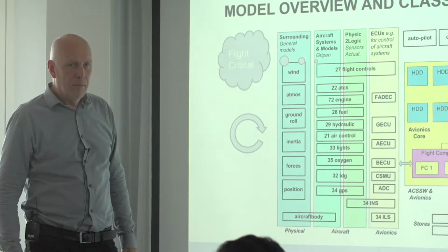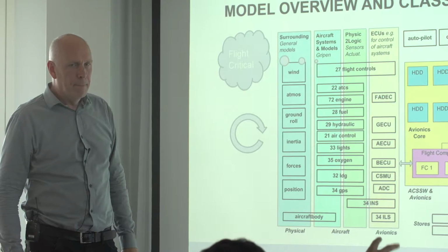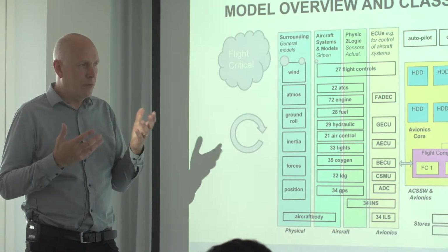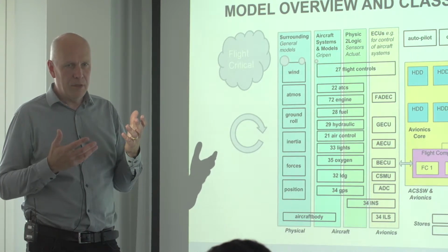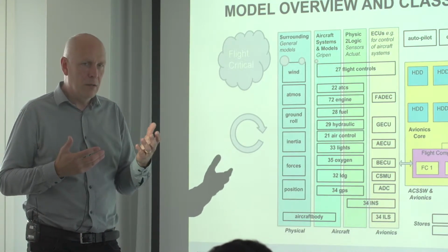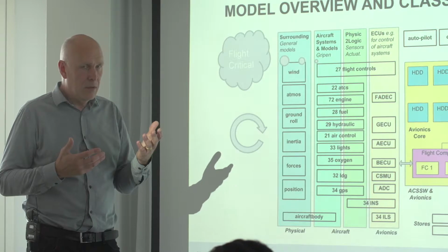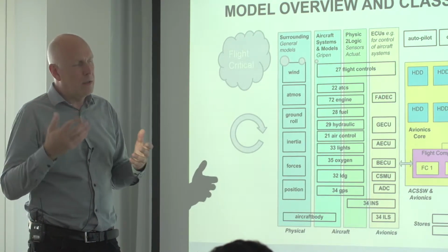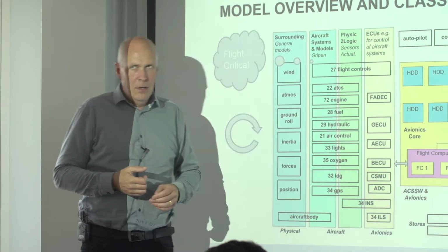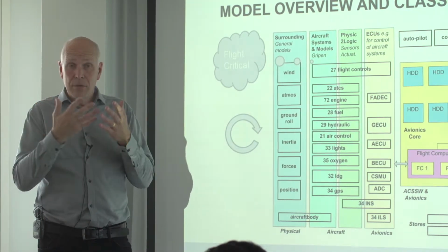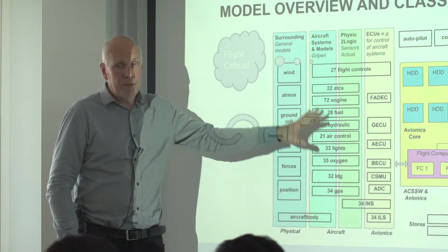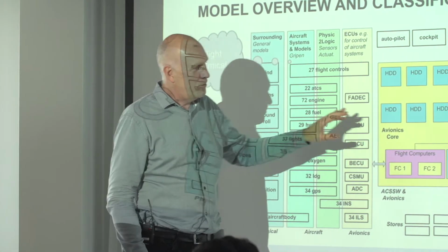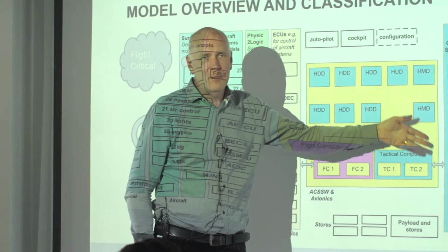What kind of information is displayed? Like the tactical information? Yeah, usually it is both. So it is the flight critical information, what height, what speed, how much fuel is left, but also the tactical information. That's also architecture-wise a challenge to mix, because we mix things coming from the safe side with things coming from that side, and what happens if these get mismatched in some way?